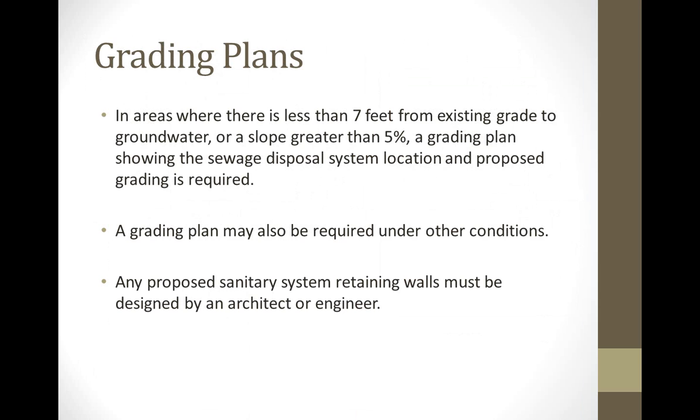In areas where there is less than 7 feet from existing grade to groundwater, or a slope greater than 5%, a grading plan showing the sewage disposal system and proposed grading is required. A grading plan may also be required during review under other conditions.